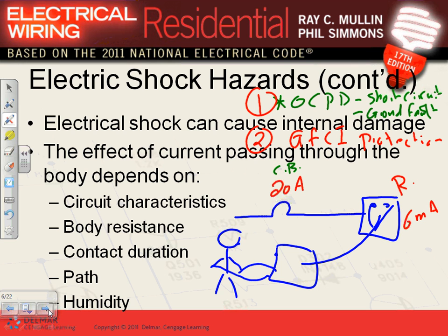Oh, ground fault. Here's a hot, and here's the ground, and you short them. The ground, it's the same as short circuit in a single phase, almost. If three phase, it becomes a short circuit, and three phase to phase too. In a single phase, the ground fault is line to ground or line to neutral too. So that's protection number one.